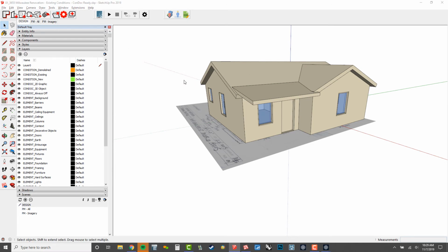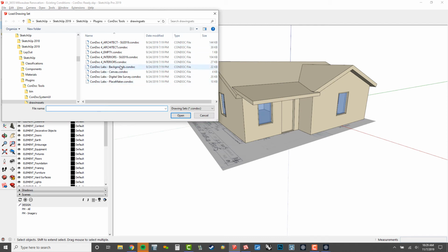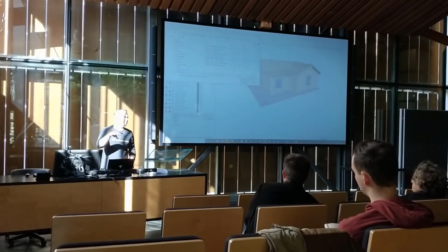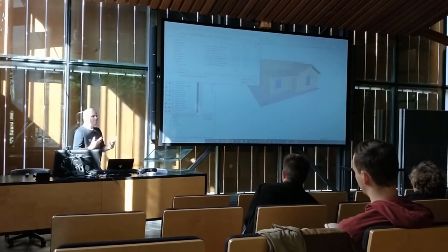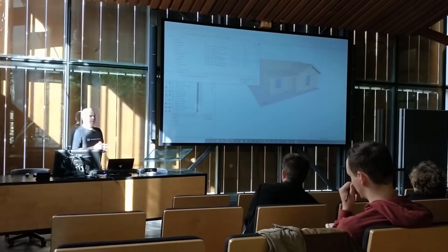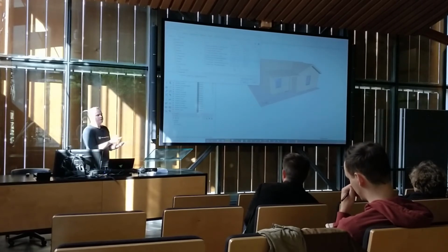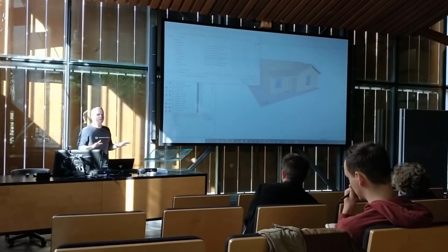And when I say these different tricks, I'll hit open again. You can see that we include a couple of different drawing sets. I've been calling them Condoc Labs because they're just these ideas that I have of what else we can do with Condoc. So one is to create background drawings for consultants, which is huge. A lot of people who want to use SketchUp and LayOut for construction documents ask, how am I going to work with consultants? No problem. We have a Condoc drawing set. It creates all the scenes that you need to export each of your different building elements into a DWG. They all XREF together. You send them to the consultants, and they don't even know that you're using SketchUp.